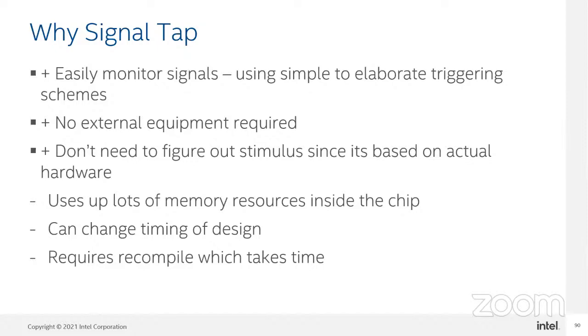Okay, what is the drawback? That's what we should also understand. What are the cons? It uses lots of memory resources inside the chip. Since you are going to use the embedded logic analyzer, which is an IP, you are going to bring that IP into your design. That IP will take some resources, some memory resources.